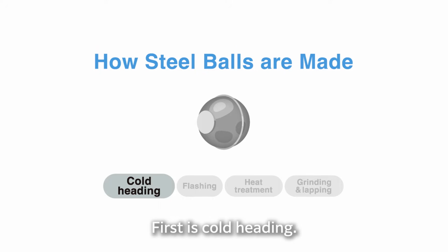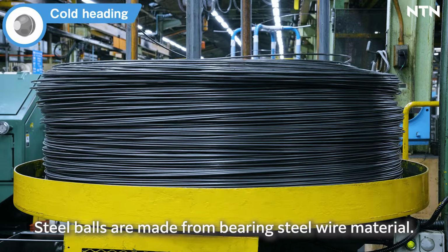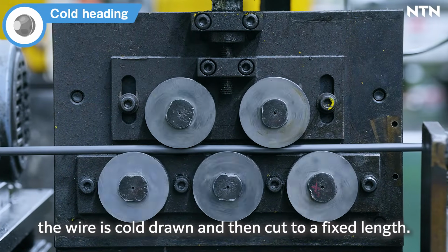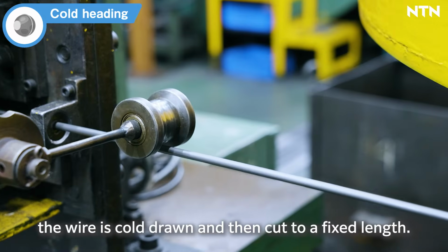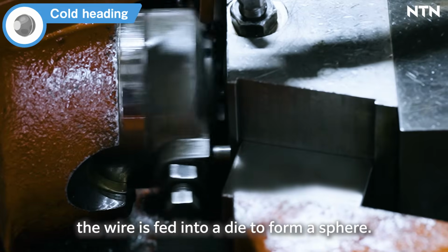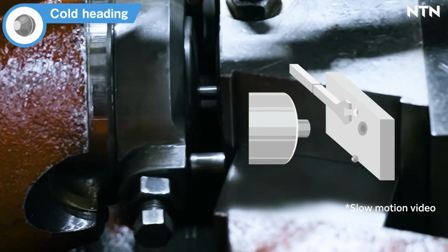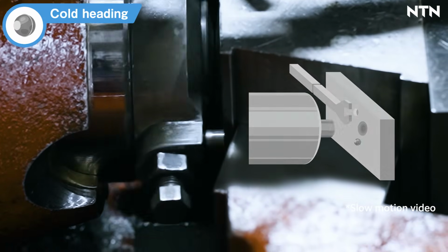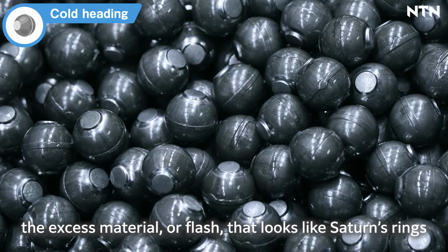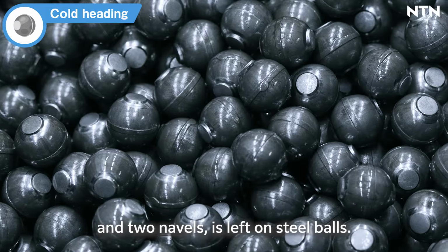First is cold heading. Steel balls are made from bearing steel wire material. In the cold heading machine, the wire is cold drawn and then cut to a fixed length. In the cold heading process, the wire is fed into a die to form a sphere. At this stage, the excess material, or flash, that looks like Saturn's rings and two navels is left on the steel balls.